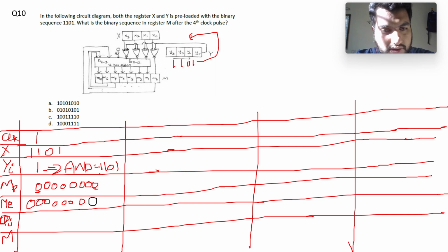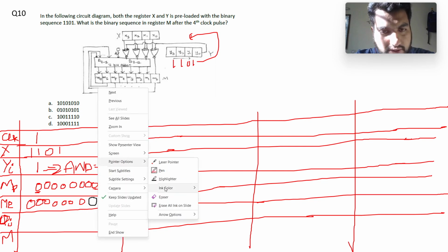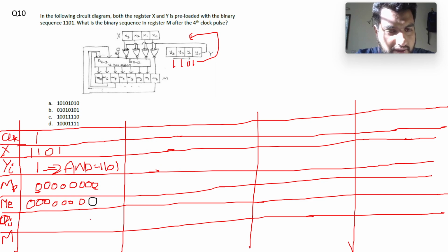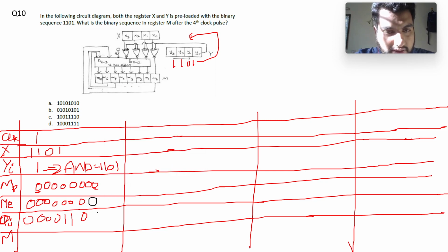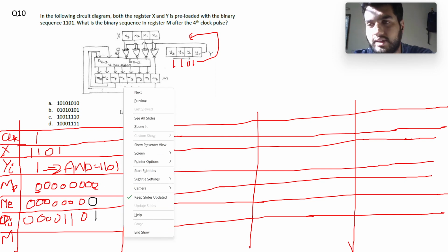And my another input that goes to the adder is AND, that is these 3 bits, that is 1 1 0 and 4 zeros from here, and I will write 1 here, this one. Input to the adder are only marked with red, keep that in mind. This black doesn't go to the adder. You can also refer to your lectures where they have marked the input to the adder as blue and the one that is not going to the adder as black, so I will just use the same color coding scheme.